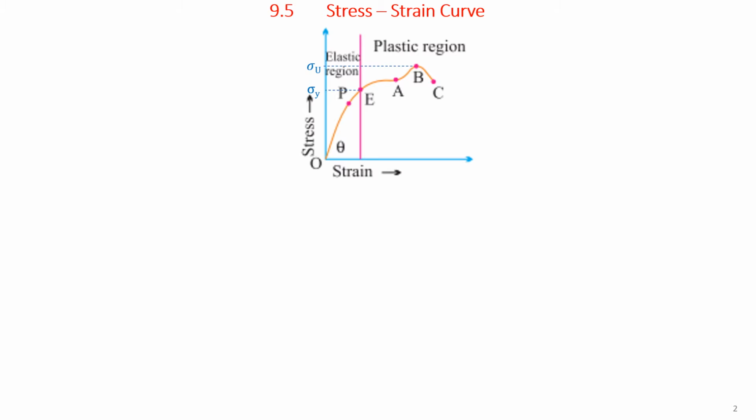The relation between stress and strain for a given test material can be found by applying a tensile force or a compression force. In a standard test of tensile properties, a test cylinder or a wire is stretched by an applied force. That means the test material can be in the form of a cylinder or a stretched wire. The fractional change in length, that is the strain, and the applied force needed to cause the strain are recorded. That is, the values of stress and strain are recorded.